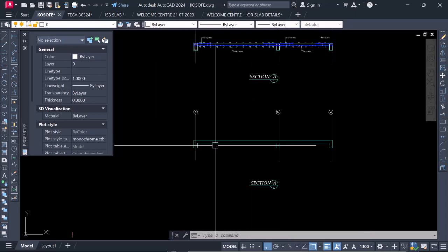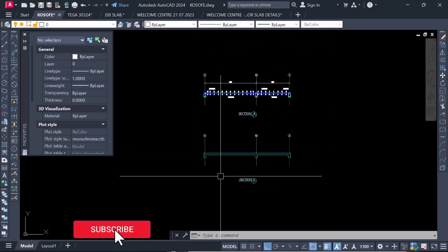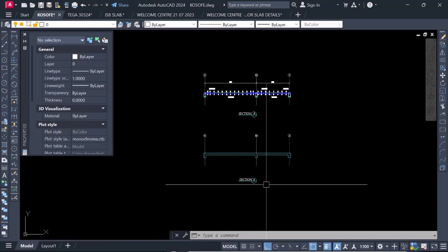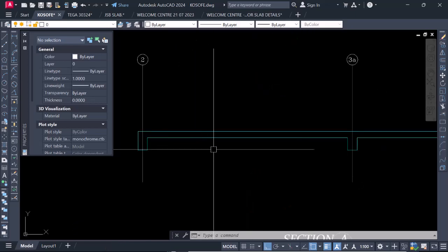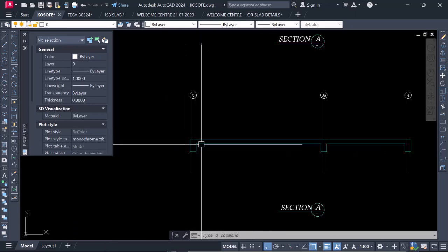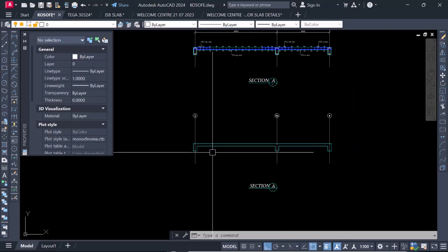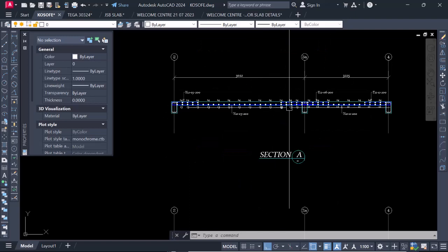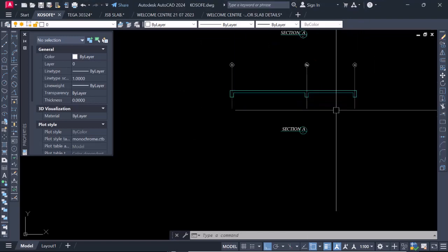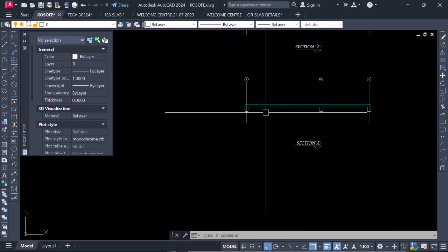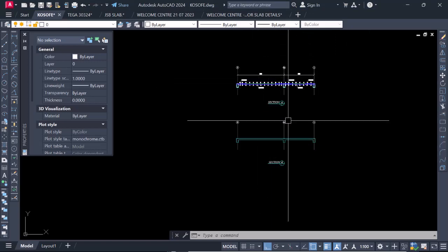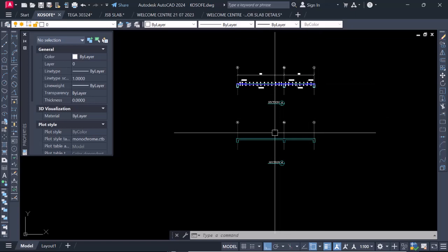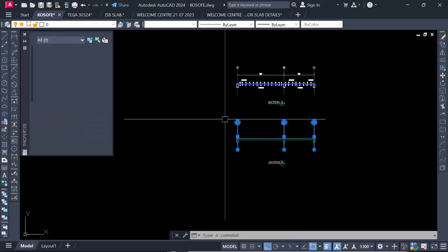So the hatching on the side, where we're going to do your drawing, should be comprehensive, like I said. We make our design very comprehensive such that the mason understands what they're going to do, and even the carpenter, seeing this, understands how the formwork is going to be done. So let's detail this before we come back to our reinforcement. I always say the section should be two: this should be the reinforcement, and this the formwork.